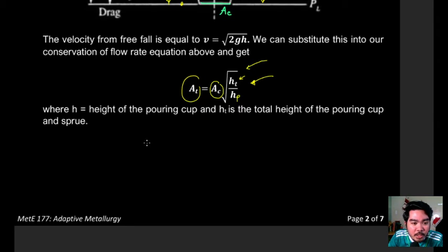graph, no? And that is why if you observe, no, kunwari, if you have a faucet, no, pangit yung drawing ko, pero this is a faucet, kunwari, if you notice a faucet, yung natural tendency ng water is to form a parang ganitong shape, tama? And this shape actually follows this equation, no? AT is equal to AC or ganyan. So that is why yung down sprues natin, usually we want it to be tapered in this manner, no?